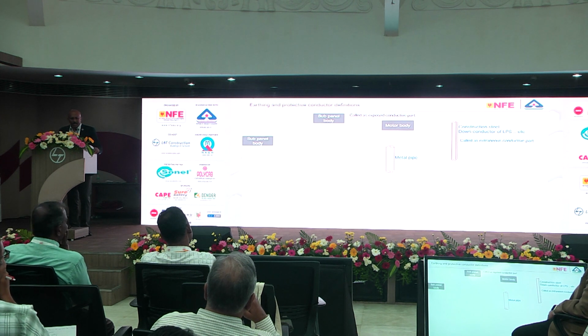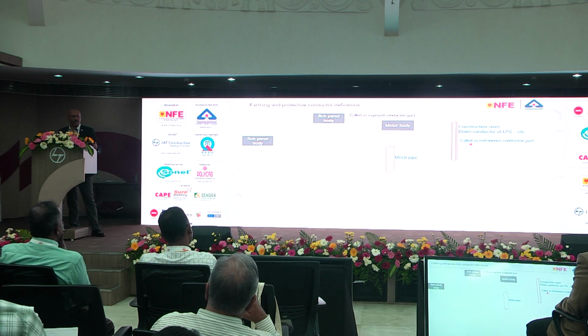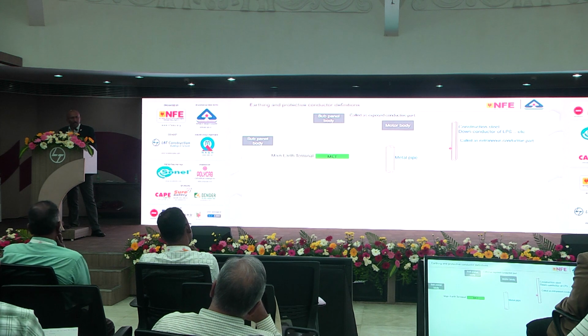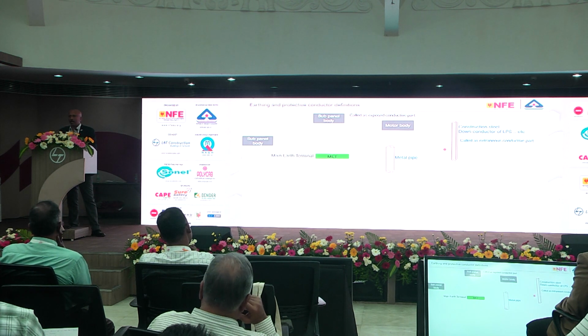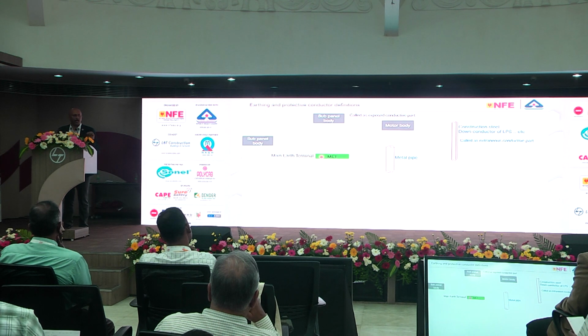So you will have, for example, sub panels, and then some kind of motor. These are technically called exposed conductive parts. Your building also has extraneous conductive parts such as building steel, metal pipe, firefighting pipe, and so on. Your job as the designer, contractor or verifier is to find out if you have an MET. The new word is MET. The old name is protective equipotential bonding terminal.